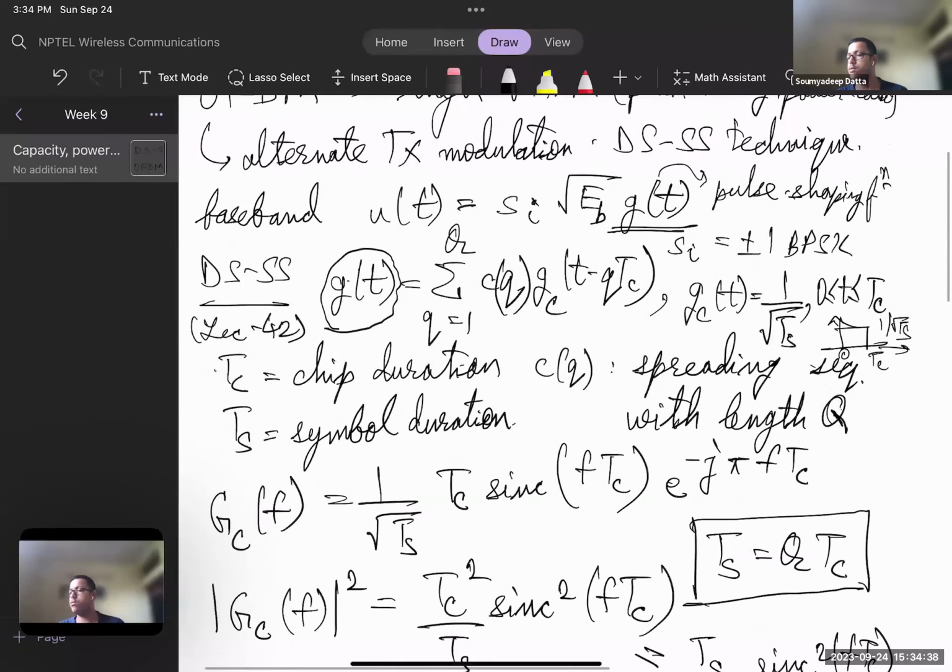So the first part, which I solved here in this question, what I'm asking you is, you are told that the symbol rate is 125 kilobaud, and you are using a DFT spread modulator, and chip duration is 2 microseconds. And you are asked to draw this. So first, you have to draw the basic one without spreading. If you have to design a modulator function here, what will that look like? So without spreading, the modulator function is exactly like this. So this is how you do the modulation.